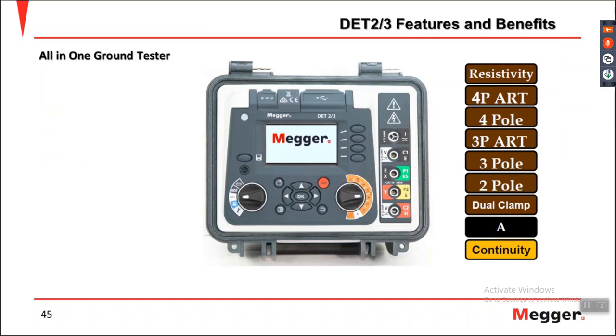And the last topic is the new grounding tester DT23, which can do testing based on some methods, or I think all methods. This equipment can do the 4-pole electrode technique, 3-pole testing with fall of potential or depth measurement, dual clamp-on methods, and can also measure current, leakage current, and continuity. This is a very good instrument because the complete set of methods can be done through this unit.